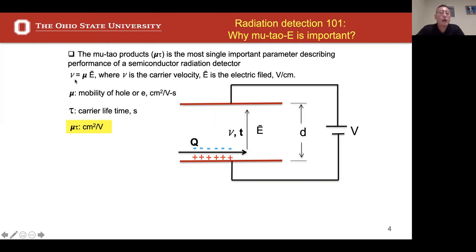So what is actually mu? Well, look at this very simple structure. I like to use this planar structure for radiation detection. This could be a semiconductor device, or it could be a gas chamber. I forgot to mention in my previous slides, when I introduced detection materials, that the most widely available, lowest cost radiation detection material is actually the air we breathe every day. That's what's been used in millions of smoke detectors for radiation detection. You can imagine here the air has high resistivity, like a semiconductor device with a depletion region, which has very high resistivity. Lots of similarity.